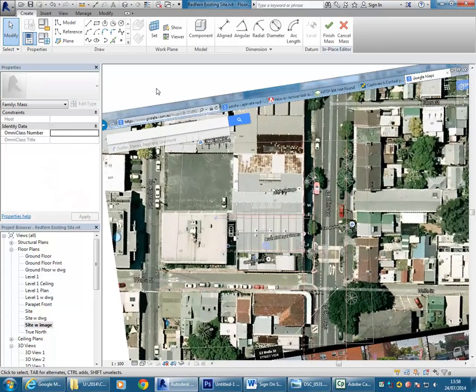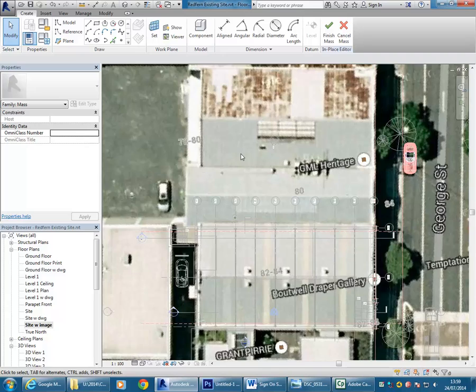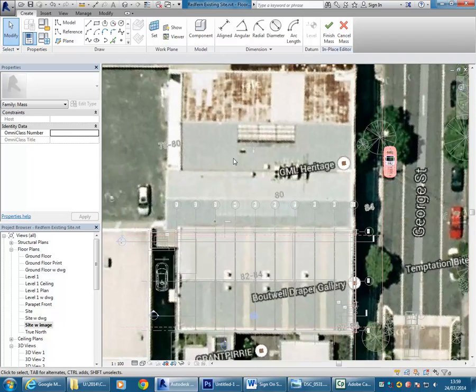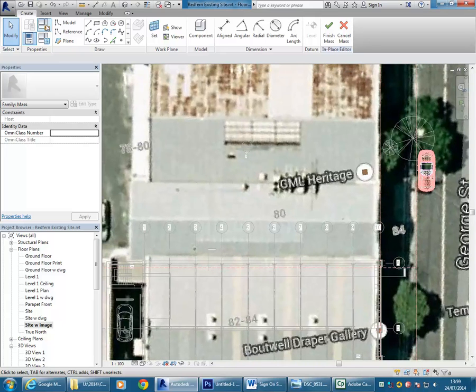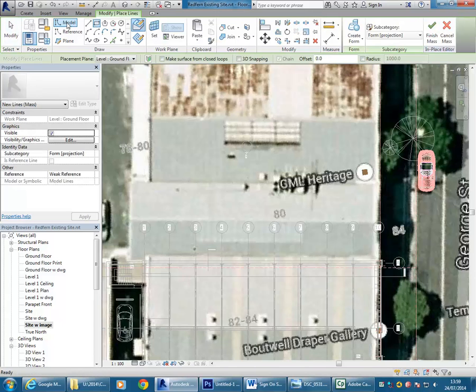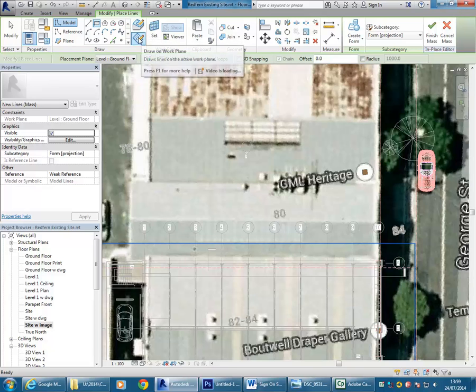And then you'll have the massing tools. Because these buildings are largely rectangular, actually, a lot of them are just rectangles, I'm going to start with that. On the Create tab, you can see you've got the Draw panel, which has all of your basic shapes. If you click on the rectangle button, it should highlight model. Make sure it does model lines for you once you click on rectangle. And then change it from Draw on Face to Draw on Work Plane. That's really, really important. You'll see that option next to the Draw panel.